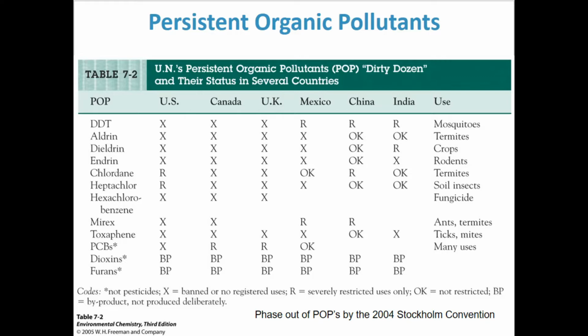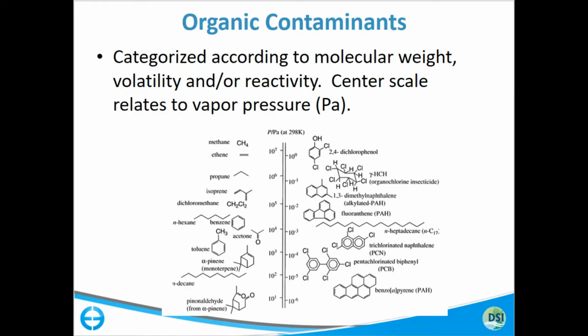So if you go back up here, if you've got benzene for instance, benzene has a density lighter than water, so it's an L-NAPL, a light non-aqueous phase liquid, and if it gets into the water column, it'll tend to float. So you have volatilization working for you, so it goes away pretty quick. And what doesn't go away, if it's in an oxygen-rich environment, biodegrades relatively easily. So benzene's not really a particular problem. Acetone, toluene are a little less volatile, a little harder to degrade. But these chemicals over here are pretty much not an issue for most toxic contaminant sites.